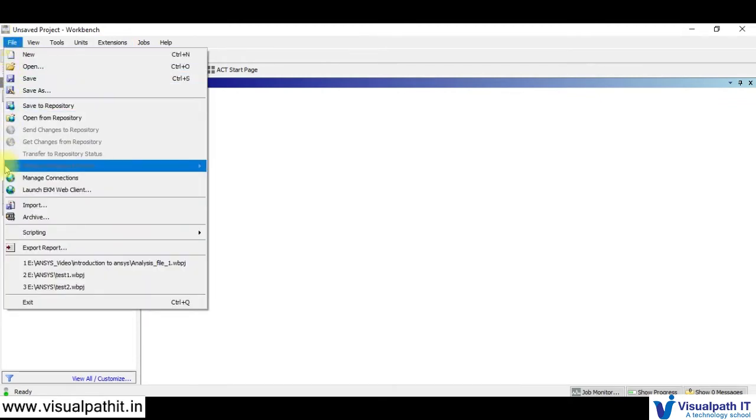Moving on, these are a kind of saved repository or web-based options which we will not be using in our day-to-day operations. Then we have import. Import and archive are two important features which we use to share files from one user to another. Import will help you to import an already archived file from a different user or from a different company, or another Workbench file that is saved and stored. That is the archive file, and import helps us to open that archived file in the project schematic.